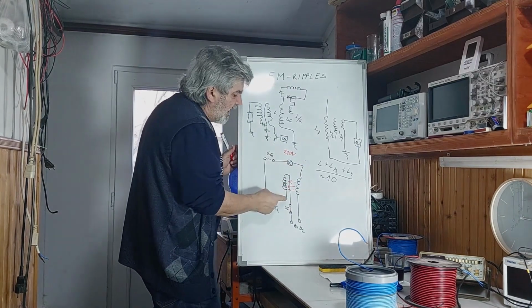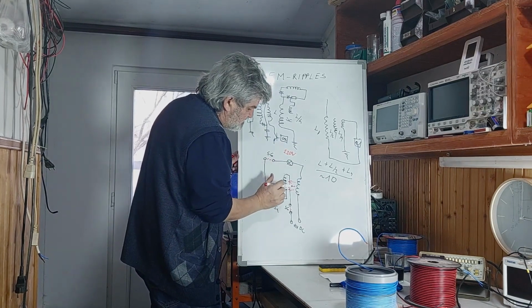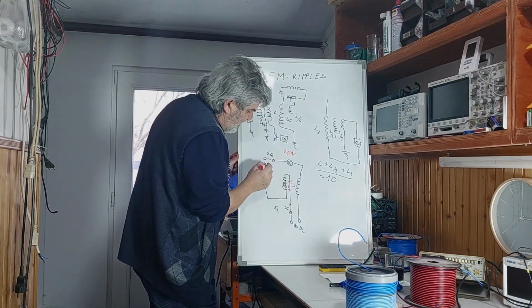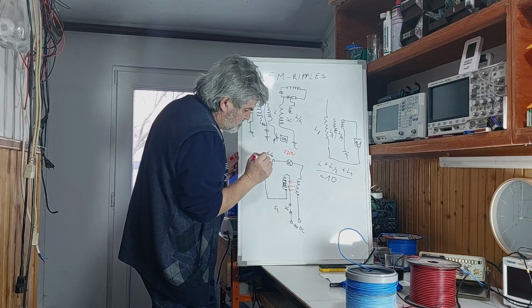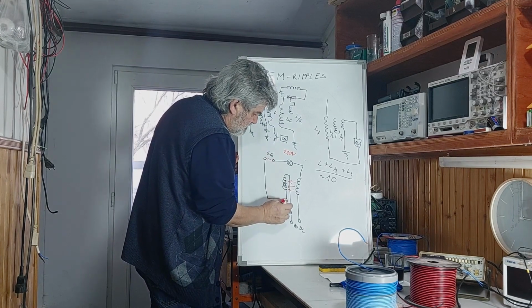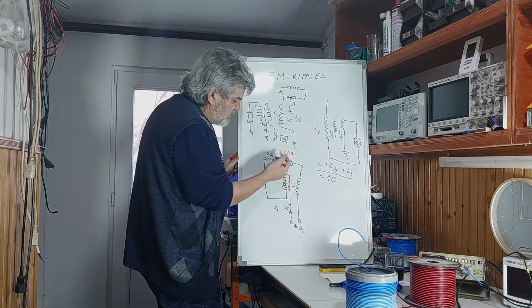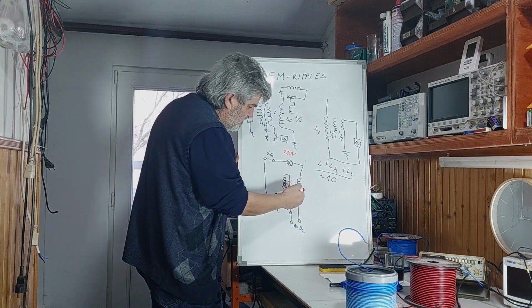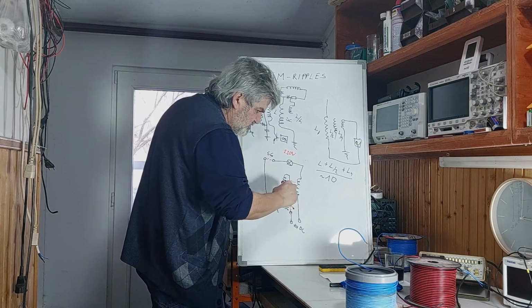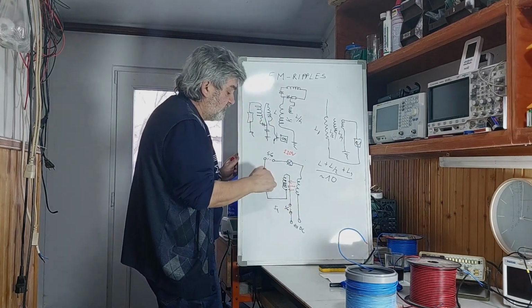But when I do that, and when the stress is enough, and the first arc jumps, let's say it jumps here, no matter where, it already energizes the coils, and it produces back EMF, higher voltage, not high current, higher voltage back.